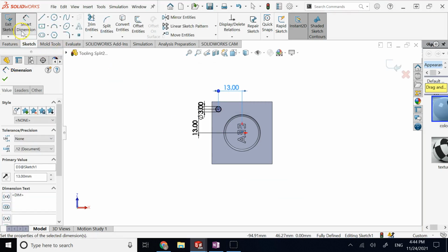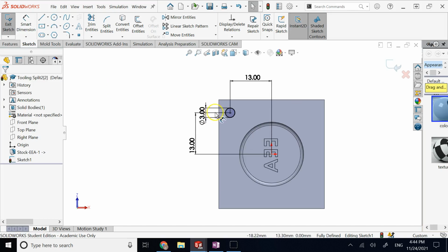And you have to also consider some tolerances here, because if this is 3 and that is 3, then they are not going to easily move inside each other. So what you need here is either a clearance fit or a transition. Definitely it's better to have a clearance fit so they can move within each other, but it should be quite tight clearance, not a very loose one, so they can hold their position relatively well.